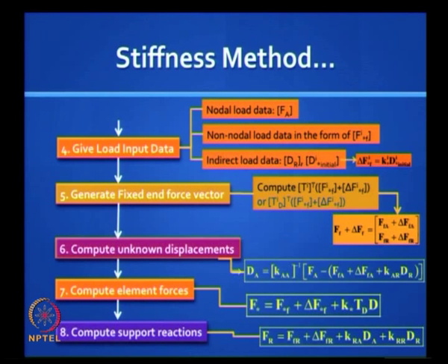Next you put in the load data, and this we will see later. You generate the fixed end force vector, you find the unknown displacements by using the inverted Ka matrix, compute the element level forces, compute the support reaction. You have got everything, and all this happens in a jiffy at the press of a button.